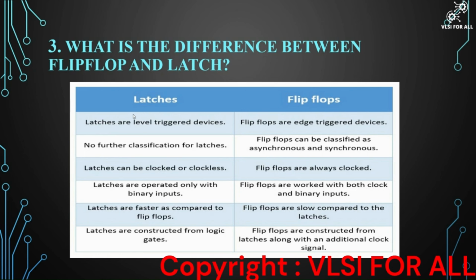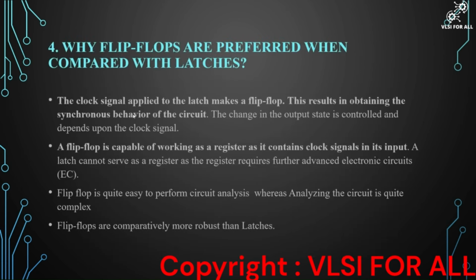Now, the next question is related to what we have just discussed. What is that question? Let's see. Why are flip-flops preferred when compared with latches? Why flip-flops? We have just discussed why. Latches do not have a clock signal. Without a clock signal, any circuit is not synchronous, and there is no timing and synchronization within the circuit. Without synchronization, how will we get the output? The change in the output state is controlled only when there is a clock signal. That is the first reason why we prefer flip-flops over latches.